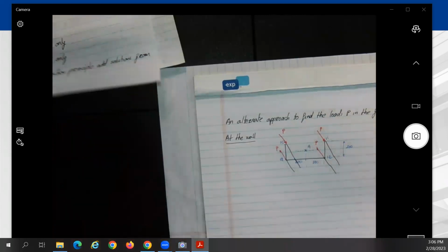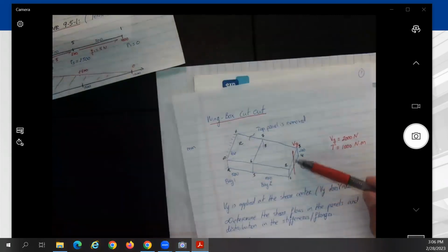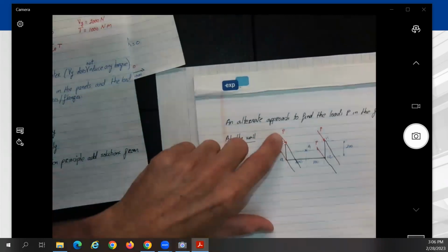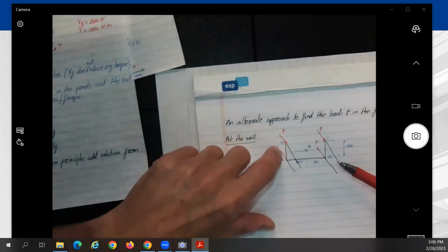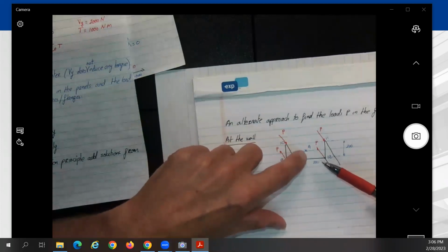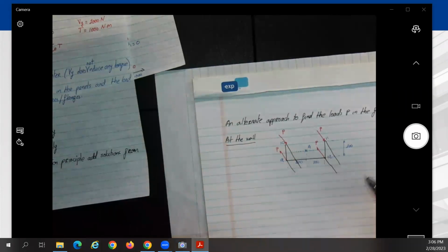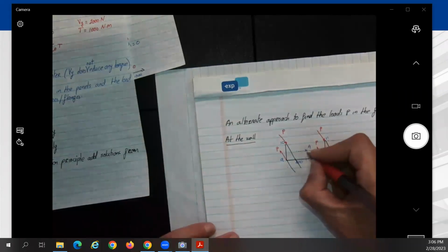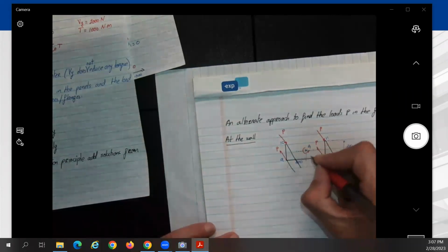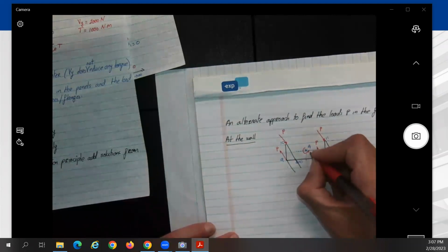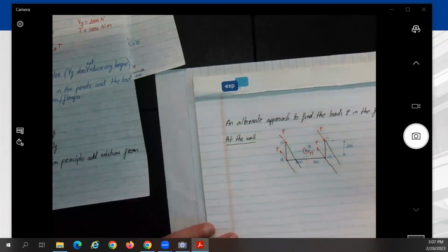So the understanding is that this force is creating bending to the top. How is it creating bending? By having these axial forces that go in the opposite direction. So they're going to create a moment about this point, along this line. Okay, so you can do it in any direction that you want. Let's say I plot it under this form. It's called this moment created by the forces P, M.